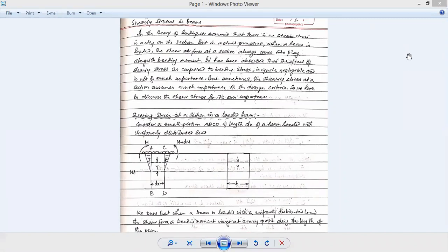But at that moment, we assumed that no shear force or vertical force acts over that infinitesimal element, which is of thickness only dx. Only the resultant bending moment created over it was used to find the neutral point, neutral line, and neutral plane, over which there is no force acting, no bending stress, tensile or compressive, which is totally neutral, and its length is not changing, even though the bar is bent.